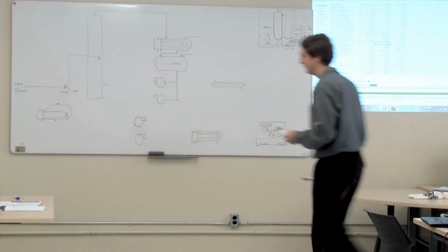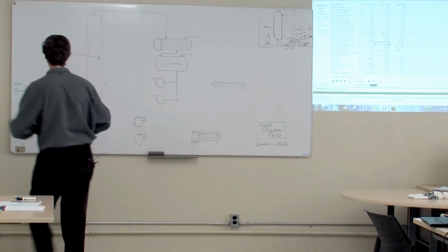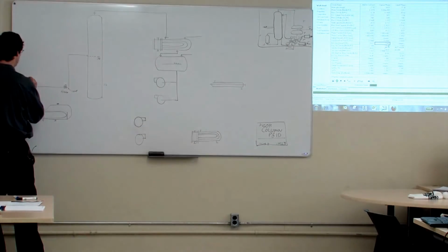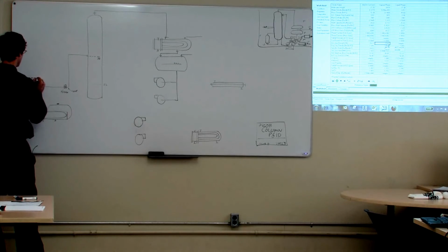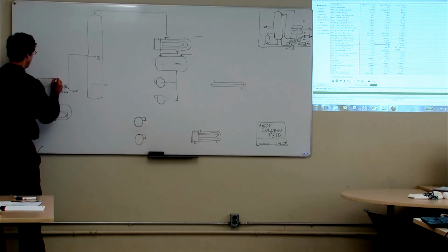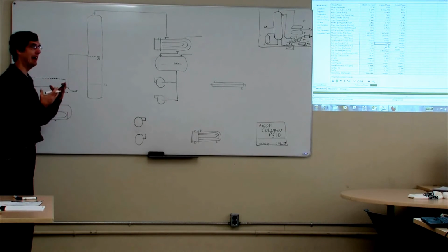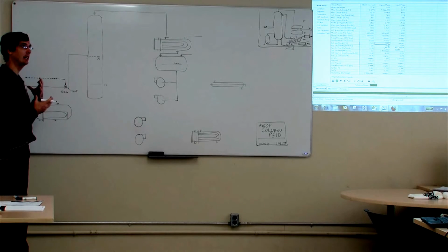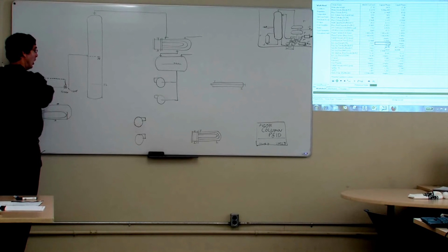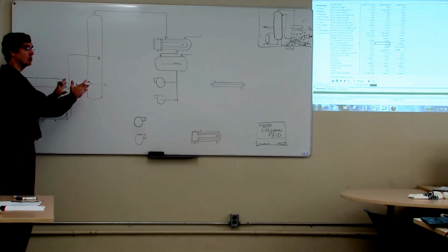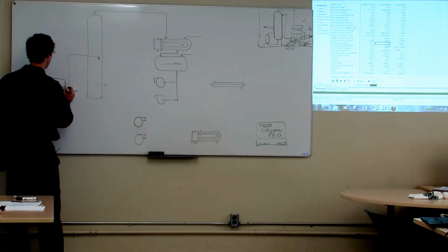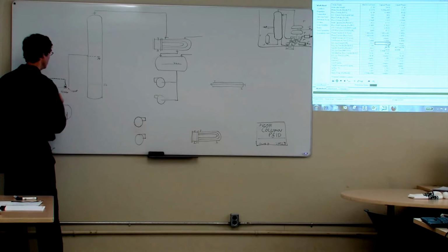Okay, so it's a hardwired signal. Oh yeah, this is great, perfect. And so it's a series of dashed lines into the valve. If I have a failure in that valve, I want to isolate. I don't want to have 60 bar or 75 bar all blow into my distillation column at the same time. I'm making that a fail-close valve. No question about it.